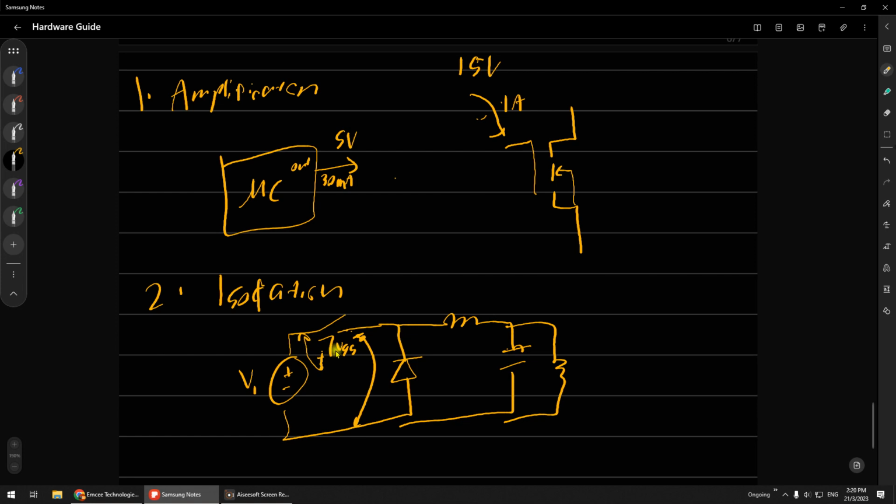So basically what happens here is you short circuit this, because it shares the same ground. That's why in this case, instead of using the same voltage source, you have to apply a new voltage supply, plus minus, where this one goes to ground and this one goes to the source, the VGS.